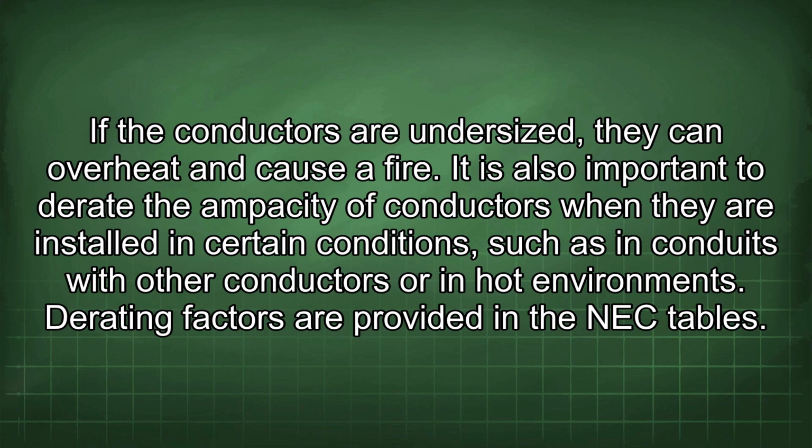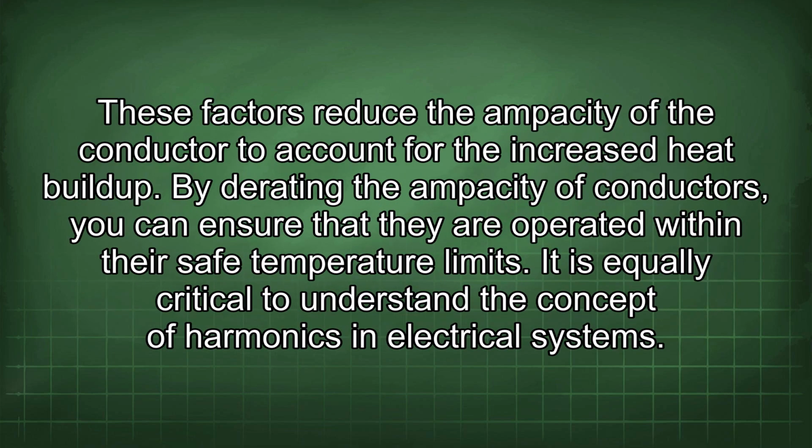It is also important to derate the ampacity of conductors when they are installed in certain conditions, such as in conduits with other conductors or in hot environments. Derating factors are provided in the NEC tables. These factors reduce the ampacity of the conductor to account for the increased heat buildup. By derating the ampacity of conductors, you can ensure that they are operated within their safe temperature limits.